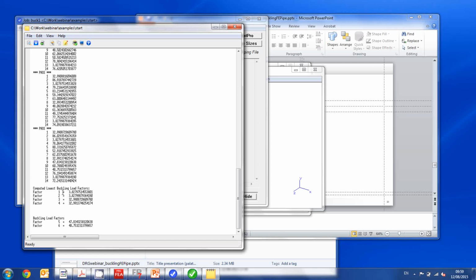You see that for the first 2 load cases, now these were the first order buckling mode, which is roughly a quarter sine wave. This has a margin, or a buckling load factor, of 3.8. So that's a factor of around 4. That means we have a safety factor of 4. So we've applied a load of 1 meganewton, and that means that the column would collapse, buckle, with an applied load of 3.8 times the applied load, so around 4 meganewtons.